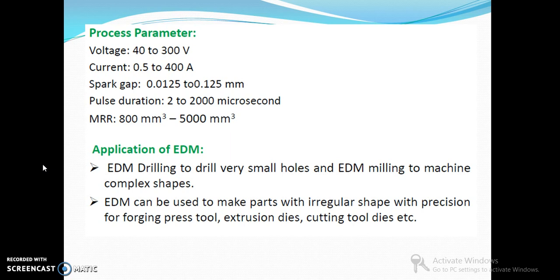Pulse duration is 2 to 2000 microseconds. Material removal rate is 800 mm³ to 5000 mm³.